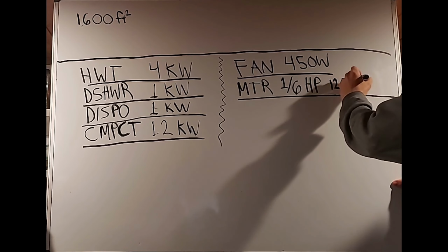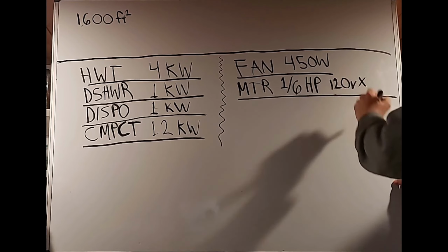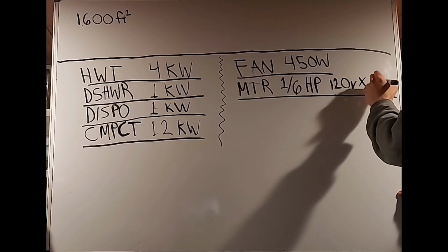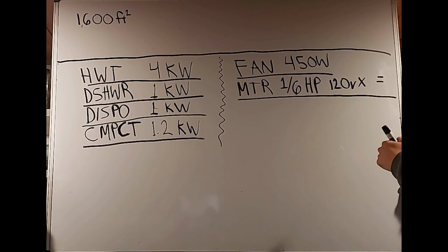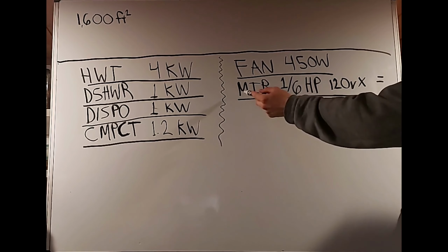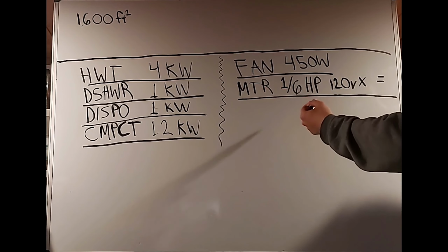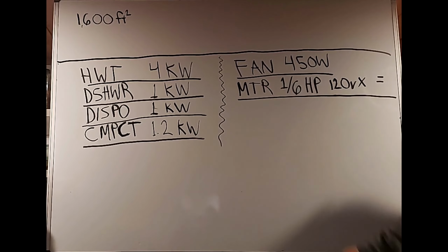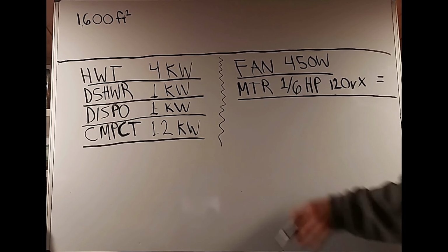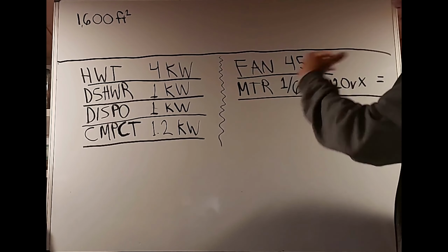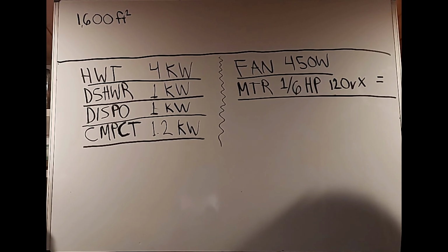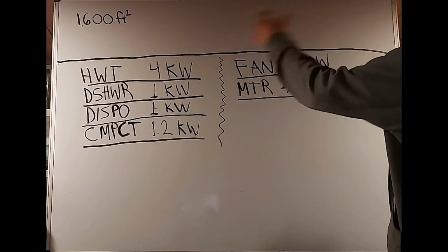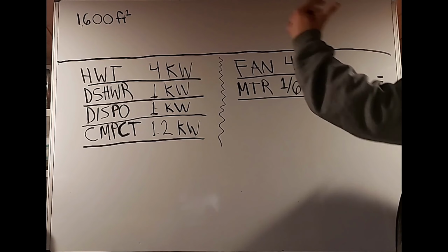Like I said, we're going to have to figure out the amps by looking in the book. When we get to this section, we're going to multiply that by our volts and we're going to get our volt amps, which will then be the rating of this motor in watts or volt amps. Here in load calculations, it's good to know that watts and volt amps are the same exact thing. We're not thinking about power factor or anything. We're just thinking about a basic overall calculation.